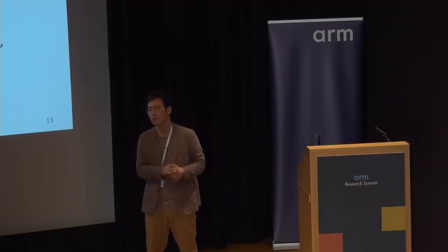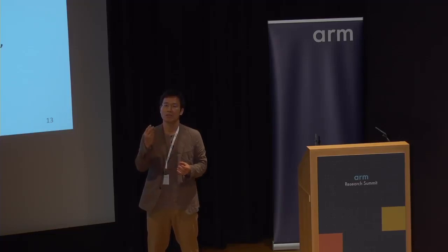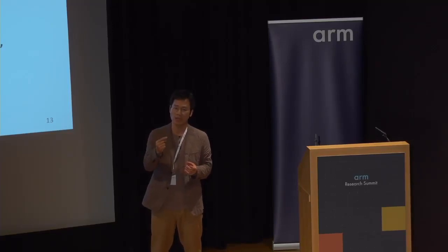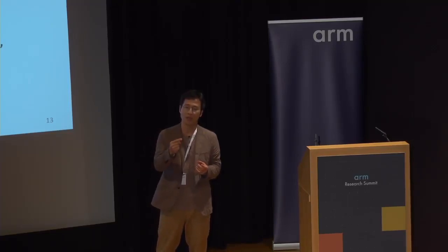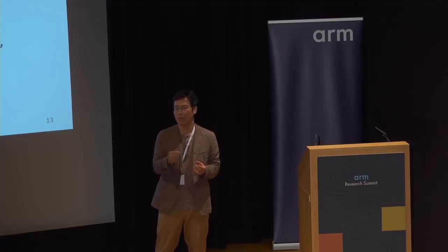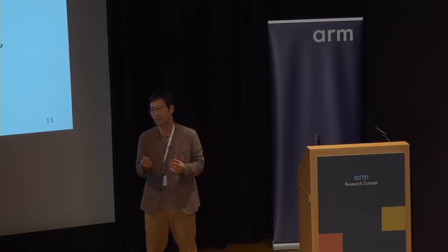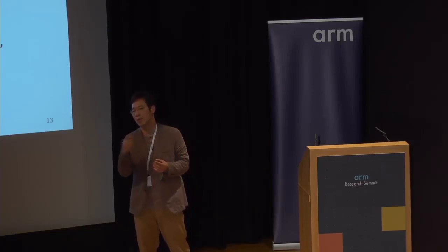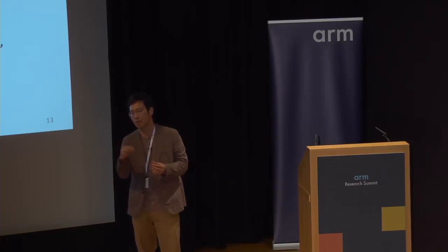We focus on load and store operations because if there is any error, it's going to affect registers, for example. And if you update memory with this erroneous value, then we cannot do anything, right? So at the memory operation, we check whether there was an error or not.